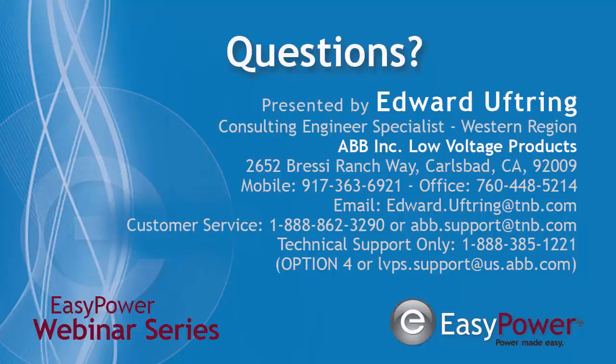However, with the electronic trip unit, when you plug in, and we also have a Bluetooth module available, so you don't even have to go to the breaker, which is a huge safety benefit. You can set it down to 0.5%. You can go to 0.675%. You can set it to any level that you want. So it gives you more accuracy in your coordination studies to go ahead and limit the current that you're putting in.